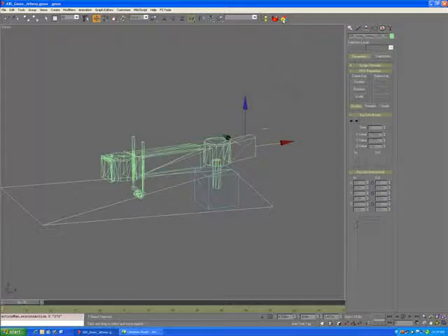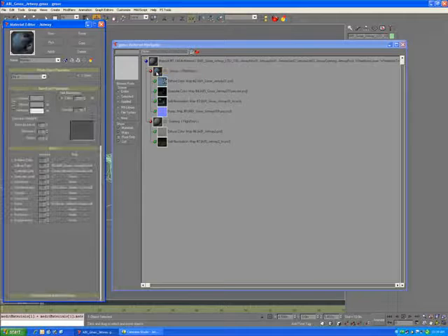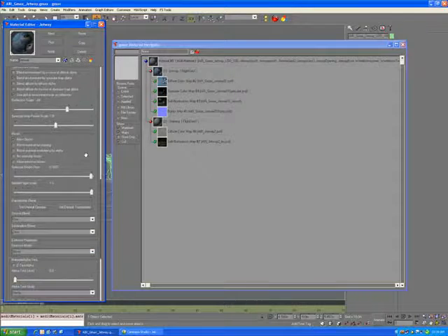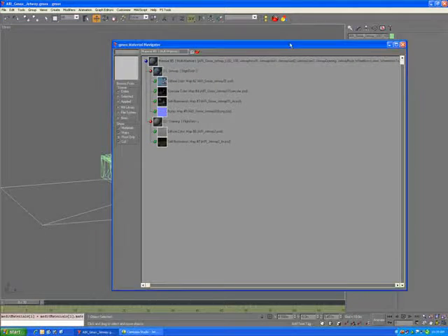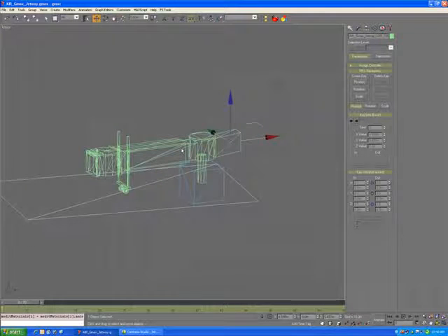So the first thing to do is to verify that your material is actually a skinned material. As you'll see, I've got the standard Jetway, specular, normal map, night texture, etc. And if you scroll all the way to the bottom, you'll see that I've got a skinned mesh selected here, and that will guarantee that when all the bones and the rig are inside it, it will skin up and act as a Jetway, but that will also take only a single draw call.